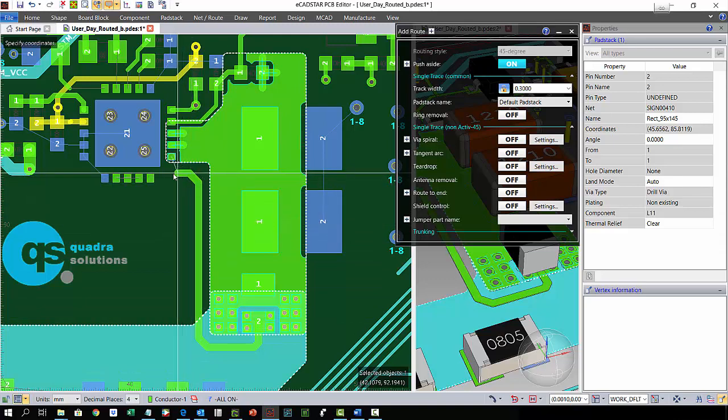The reason we've isolated these 2 pads is because the rectifier has an inbuilt current monitoring facility. If the pad that measures the current is connected directly to the copper flood, then the measurement will be inaccurate. We need to measure as closely as possible to the final output stage before the conductor travels around delivering its power to the receiving circuits. eCADSTAR's flexibility regarding the thermal, flooded and isolated connections makes this really easy for us.